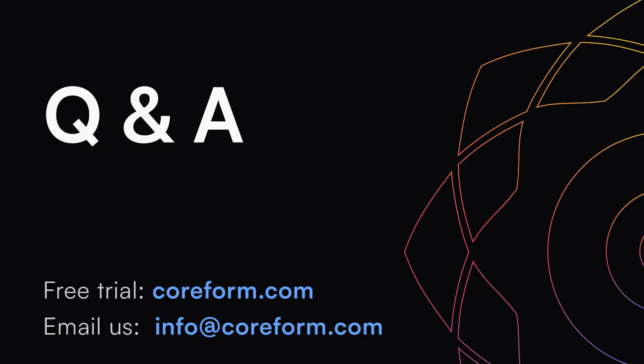That analysis took 45 minutes to run. I set a maximum time step increment of 0.1, and I started at 0.01 with automatic stepping. So without any cutbacks, it stepped up to my maximum time increment and then stepped at that 0.1 time increment for each of the steps. If I didn't want as much time resolution, it would have solved faster.